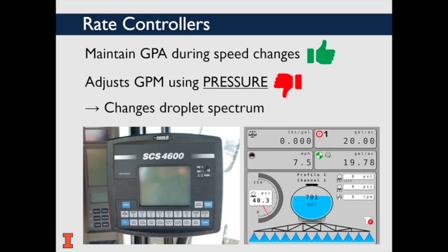During speed changes of the sprayer, a rate controller maintains application rate uniformity across the field by adjusting flow rate. If the number and size of nozzles are unchanged, a higher flow rate will generate increased pressure. As we've discussed earlier, higher pressure creates smaller droplets and effectively more drift potential. The bottom line is that rate controllers help us do a better job by making up for small variations in speed, but can create drift issues if operated much faster than its calibrated travel speed.